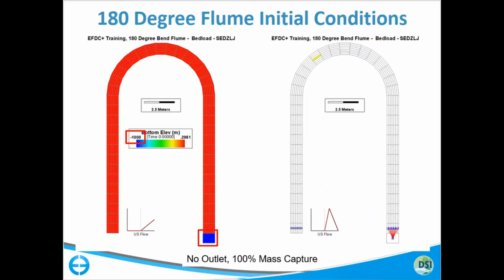So here are the boundary conditions. This is just a hydrograph that basically goes up for 1 hour and down for 2 hours. This is the actual hydrograph test case. Water's coming in at the upstream end uniformly distributed, and downstream we have hydraulic control structures. So we're taking the water that comes into that cell and just passing it down, they're all going into the same cell downstream. So we fully have a closed system.